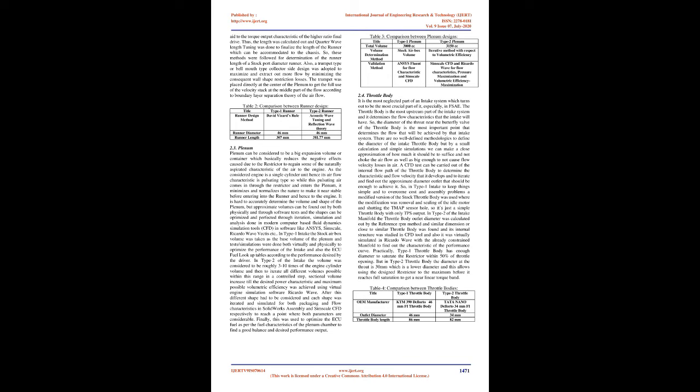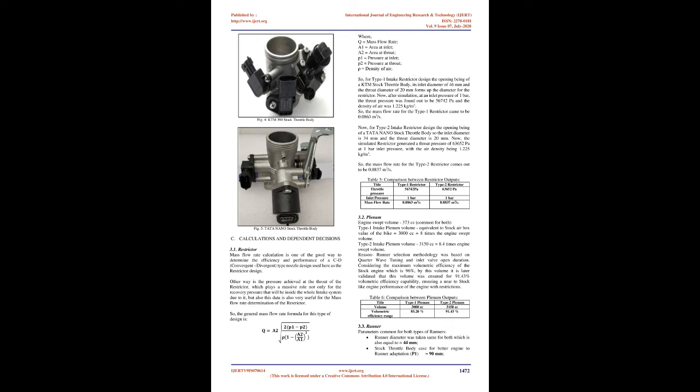In Type 2 of the intake, the volume was considered to be roughly 3 to 10 times the engine cylinder volume, and then to iterate all different volumes possible within this range in a controlled step. Sectional volume increase till the desired power characteristic and maximum possible volumetric efficiency was achieved using virtual engine simulation